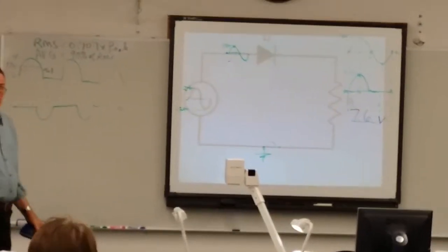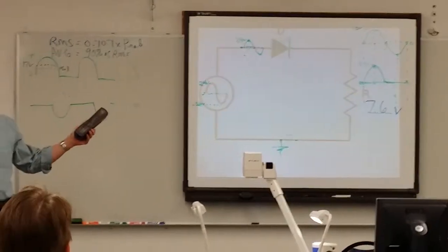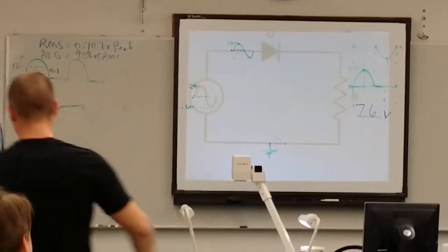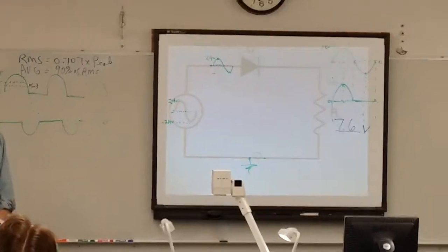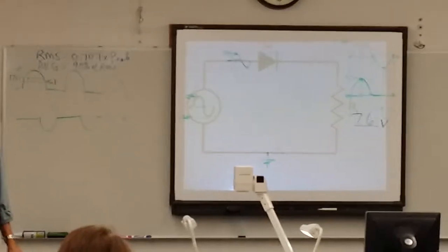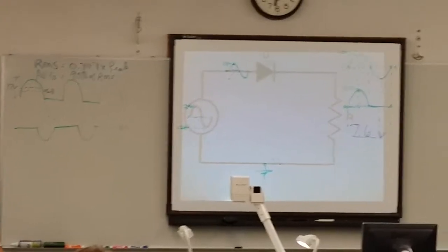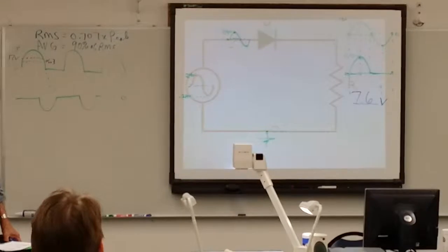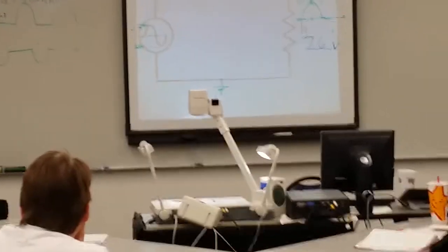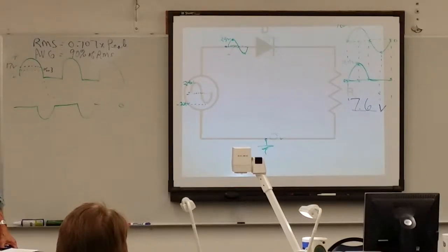If you overcharge the battery, doesn't it take away some of its life though? Sure. How are you gonna overcharge it though? If you use a 2-amp transformer here, you have to limit the current to 2 amps. Anytime you're charging a car battery at 1 amp or so, you can charge it at 1 amp for a month. In fact, I've had batteries out of my tractors. If I'm not driving the tractor all winter, I take the battery out, put it in my basement, and put it on a trickle charge for the entire winter.